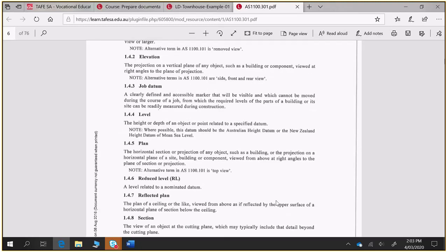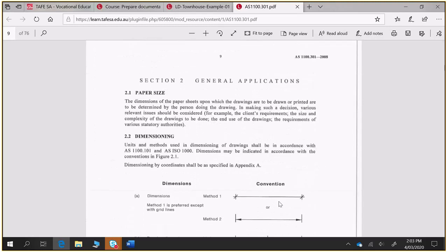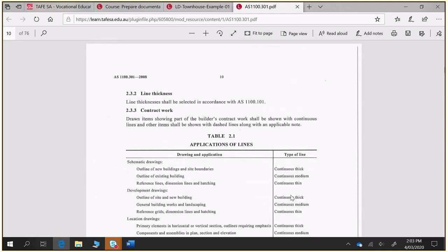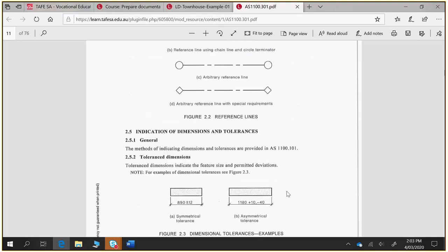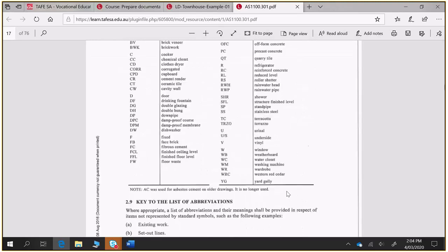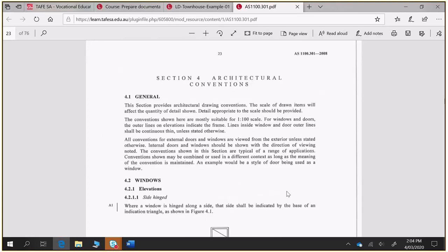Some important things to note from this are drawing conventions in terms of referencing things or for doing door swings or sections or something like that. The reason for that is you don't want them to be misinterpreted, particularly for doors and windows. That's absolutely essential. I'll see if I can scroll through to find the door and window swing section. Here we are.